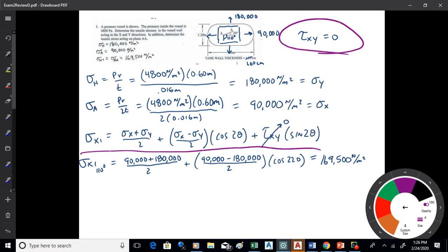And so what I'm doing here, if you'll notice, is I'm starting at the vertical plane, because by convention that's how you measure the angles for stress. So even though I gave you 20 degrees, that's not the angle you plug into the formula. You plug in the angle from the vertical plane, counterclockwise. And that's 110, 20 plus 90 more. So just remember to do that, okay?